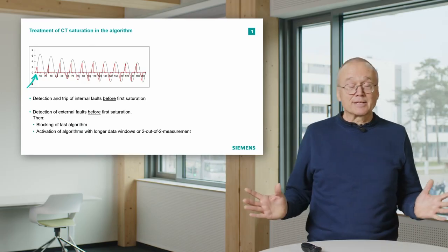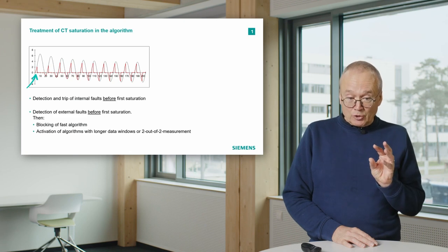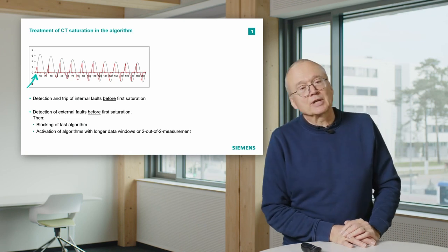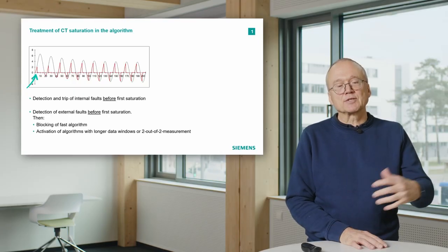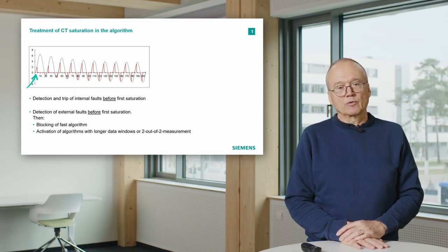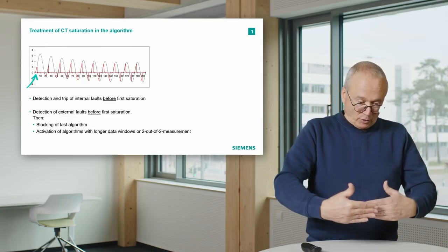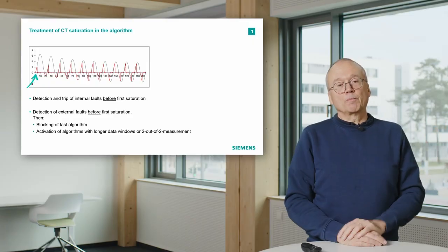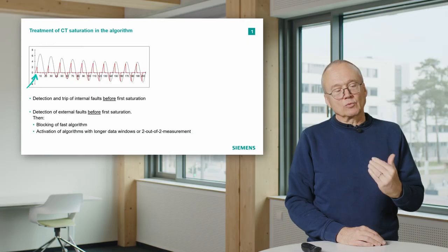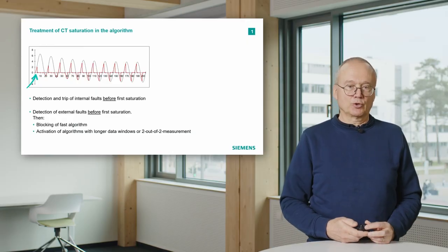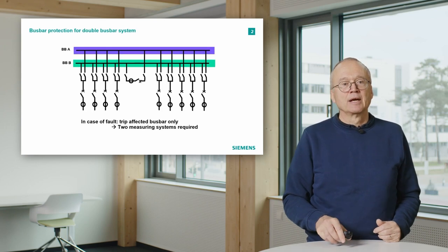You see, there is some challenge in the algorithms there, especially because normally the requirement for busbar protection is it should be very fast. We are talking here really about milliseconds. For the reaction time, of course, you have to add to that before you have the tripping time, the breakers have to open and so on. But busbar protection is the type of protection with really the highest requirements concerning tripping time. Those were the challenges concerning the algorithm.